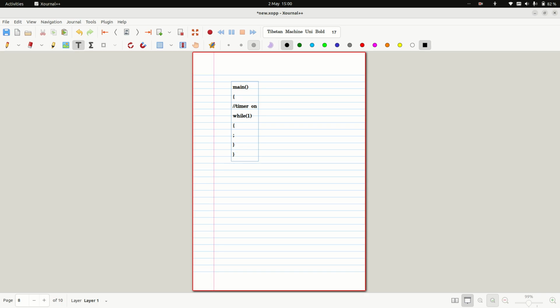Do you think this happens in a real time scenario? Yes, it happens. So how does that happen? After 255 it will roll back to 0. Before roll back, it generates INT and it tells I am full, please read the value. So whenever INT is generated, control goes to the ISR. Meanwhile, what does the timer do? Again it starts counting 0 to 1, 1 to 2. So after how many ticks is INT generated? It is generated after 256 ticks.